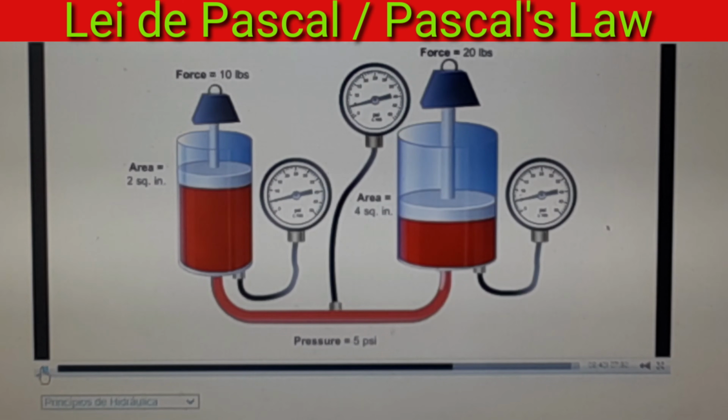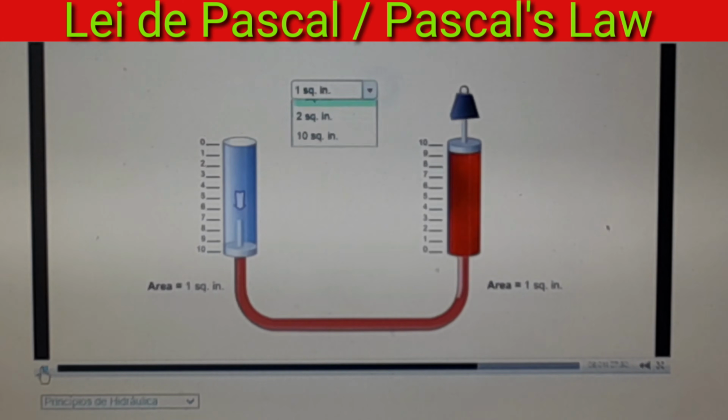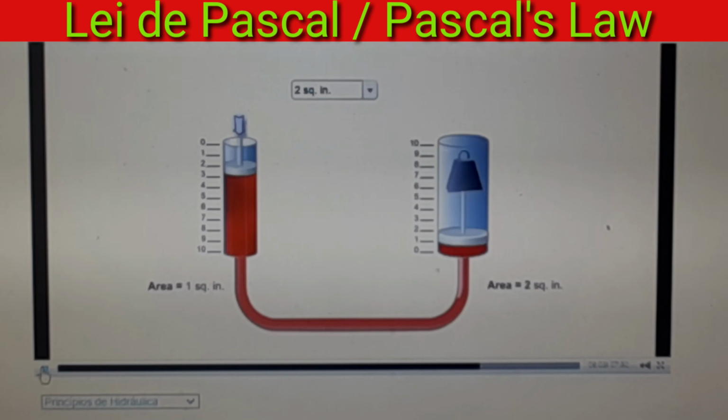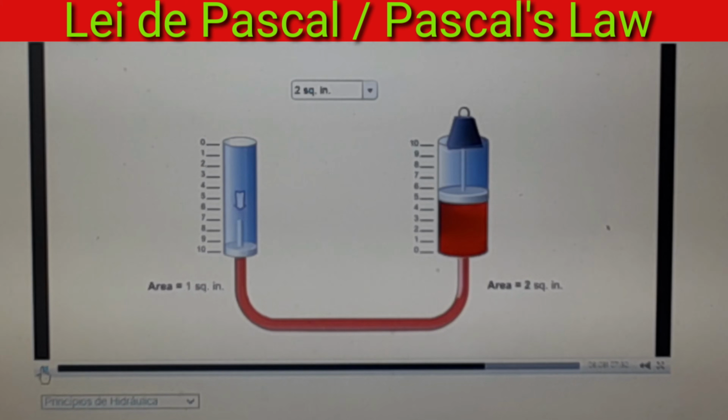By manipulating the force, pressure, and surface area, engineers can create highly efficient circuits able to produce a great deal of work. By now you know many factors that affect the design of hydraulic circuits. For example, you know that pressure exerted on a large piston will create more force than the same pressure exerted on a small piston. There is a trade-off between force and distance. Less force exerted over a large distance is equivalent to more force exerted over a small distance.